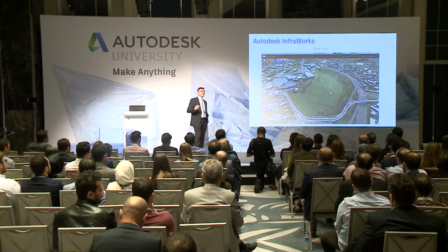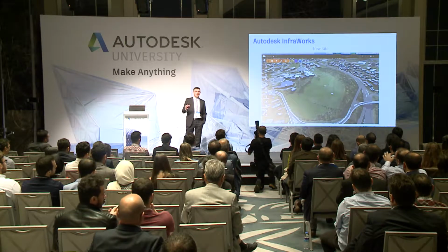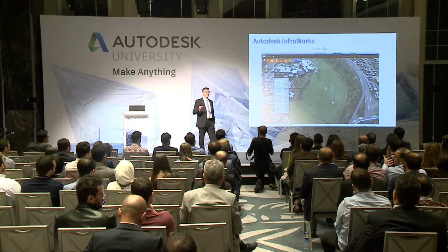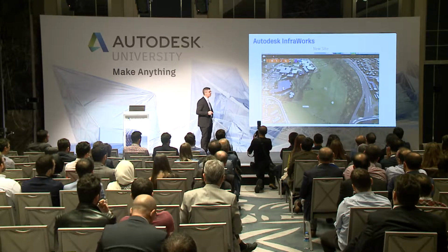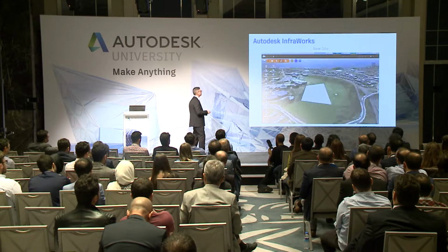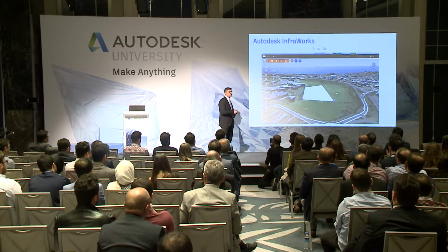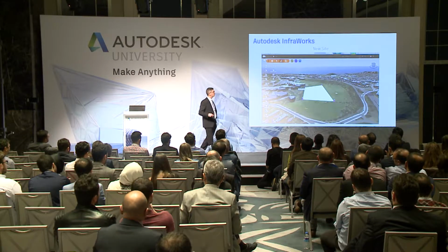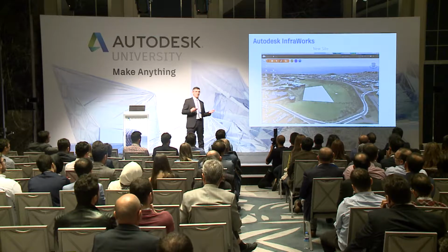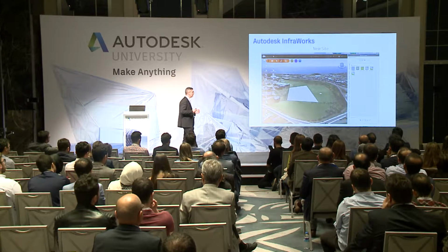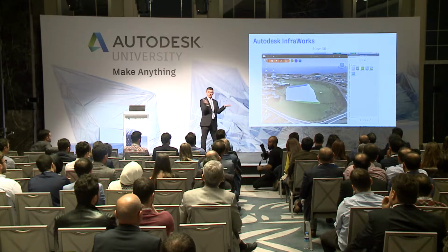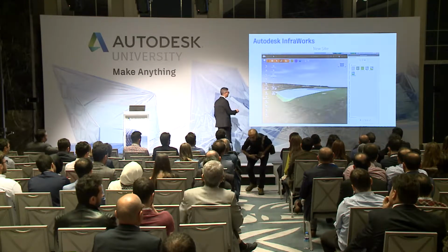But maybe you are a building specialist. Then I think it's more important to understand what it means if you want to create a new site. We have elements to create this type of site, like this. The element is a coverage area. The coverage area means that we can assign the elevation, the style, and not only the style, but the rules that manage the intersection from your floor, the elevation of your floor, and the intersection with the terrain, like this.